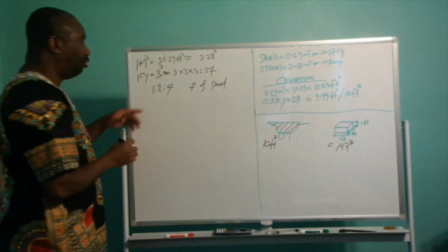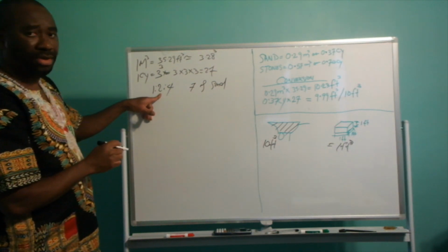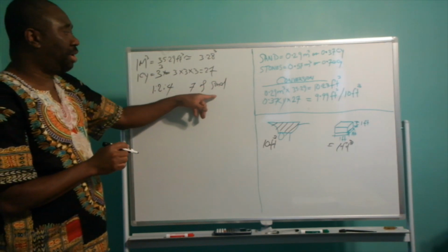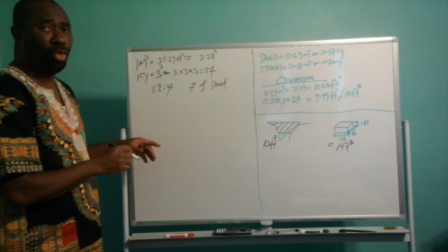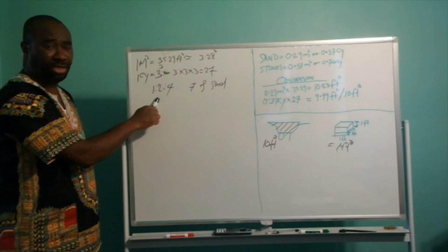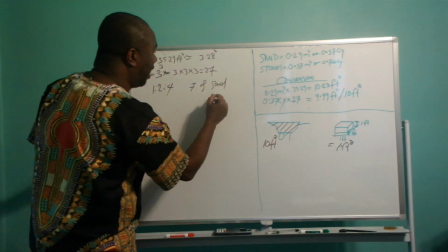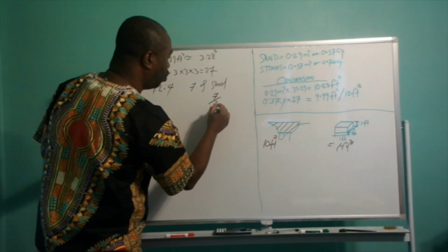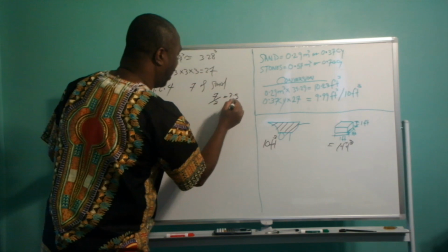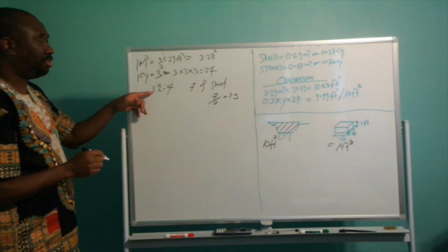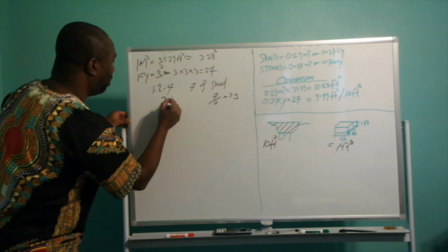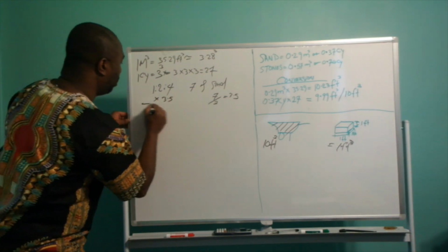And remember now, the 2 in the mix proportion is for your sand. So if you run on 7 barrels of sand, you now would have to find out the multiplying factor of your ratio, right? So you will have to divide this 7 by 2, and the result of that is 3.5. So you would have to times this ratio by 3.5 to get a consistent mix proportion.